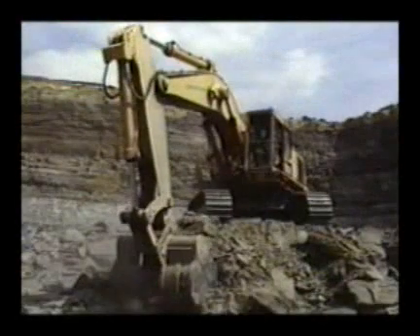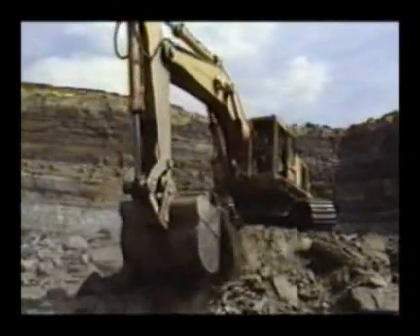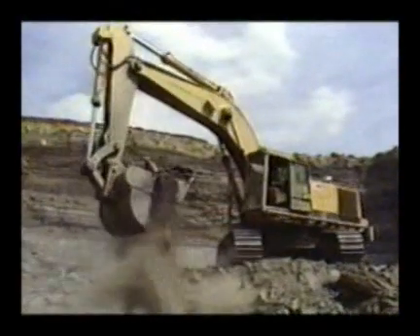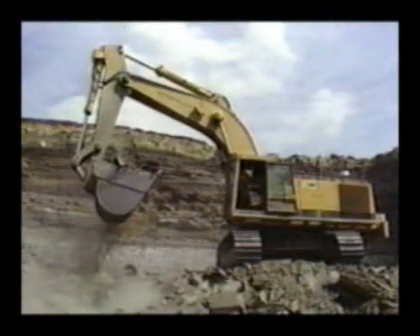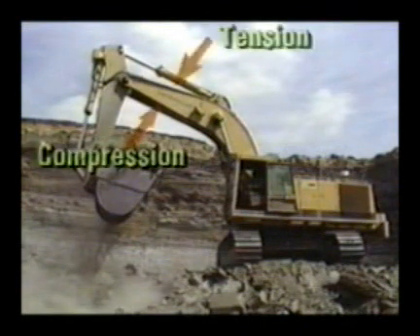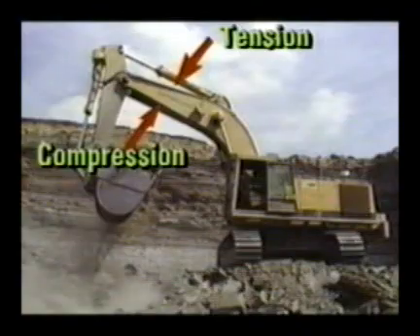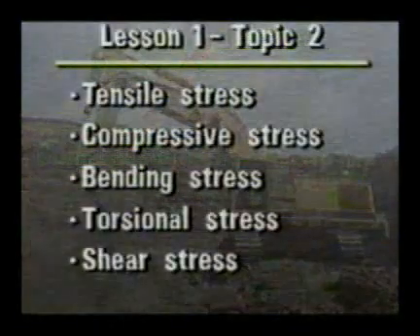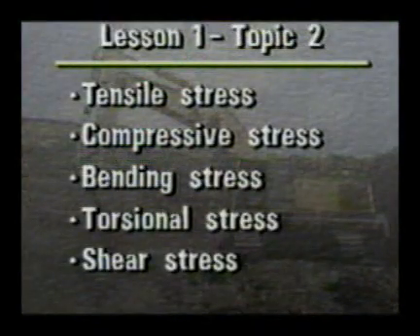Can you identify the type of load this excavator boom is experiencing and describe the internal lines of stress? If you said bending load and described the lines of stress as tension on the top side, compression on the bottom side, and zero in the middle, you have a good understanding of the type of loads and the lines of stress they generate. In this topic, we learned that each load type generates a specific stress distribution inside a part.